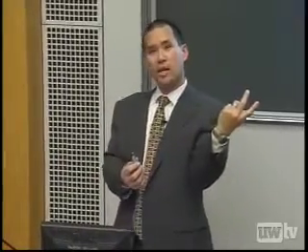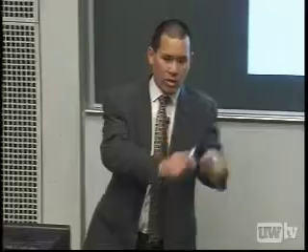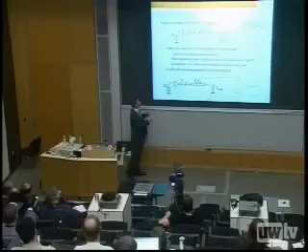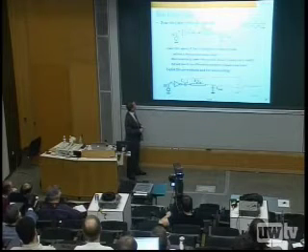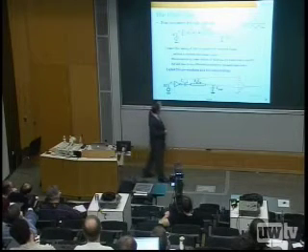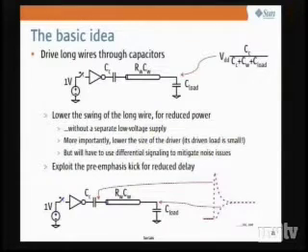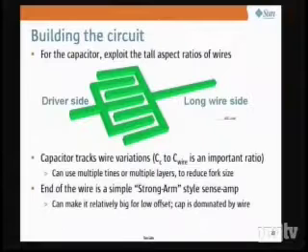Now that's nice because now I don't have low energy in the wire and this big honking driver to drive it. The driver is also reduced in size. So net, I win in power for the entire system. In addition, that capacitor gives me a pre-emphasis kick because it's an AC short. So if I swing this voltage from 0 to 1 by this inverter, the node here will actually overshoot by quite a bit, pre-emphasis, or de-emphasis perhaps, making this rise a little faster. So it's a little bit faster and it's lower energy. All right, so that seems to be interesting.